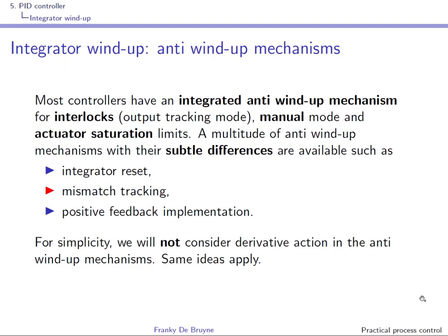Well, if you take a controller from a library, from a vendor, you will see that it has an integrated anti-wind up mechanism, for instance for interlocks, for manual mode, and for saturation. If you have to implement your own PID controller, you will have to implement this anti-wind up mechanism yourself. And this is what we'll do next.